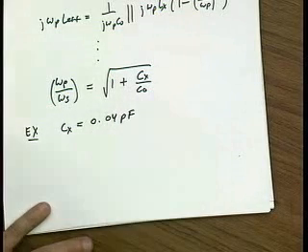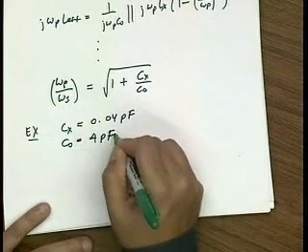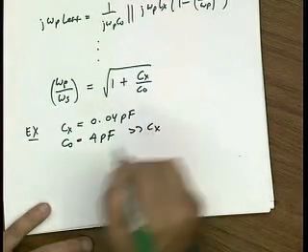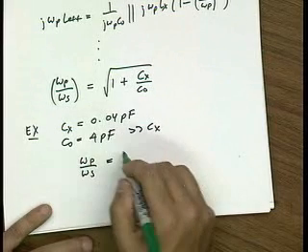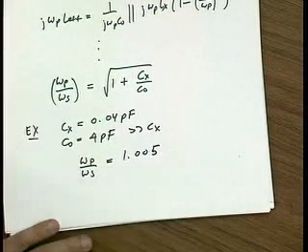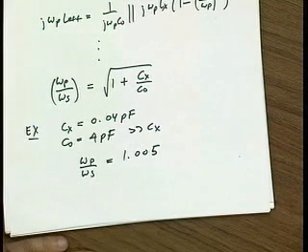Cx is 0.04 picofarads, C naught is 4 picofarads, so much bigger than Cx. And numerically that corresponds to a ratio of 1.005. So extremely small. So these frequencies are indeed very close together.